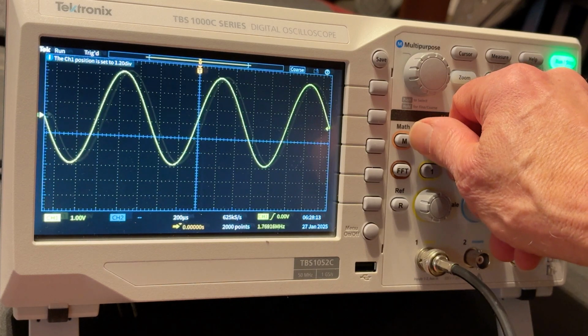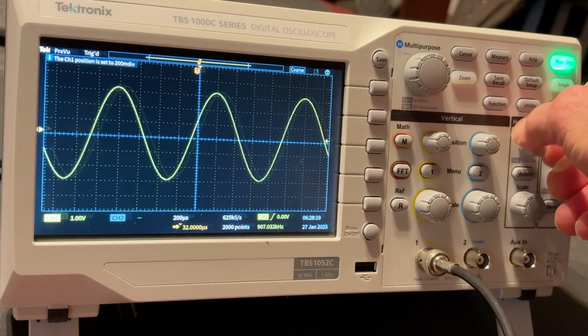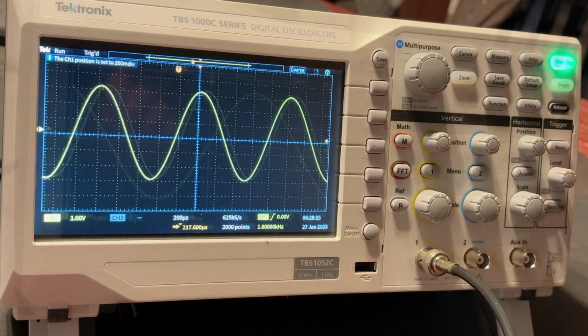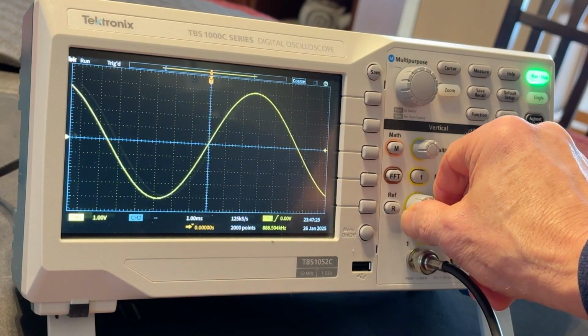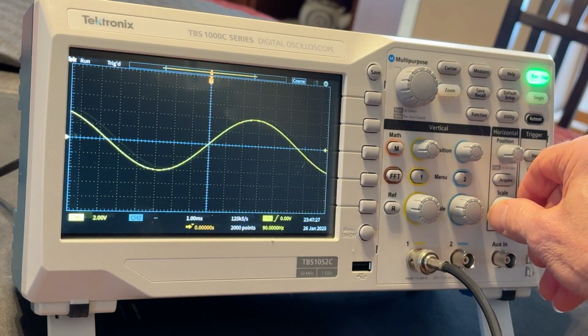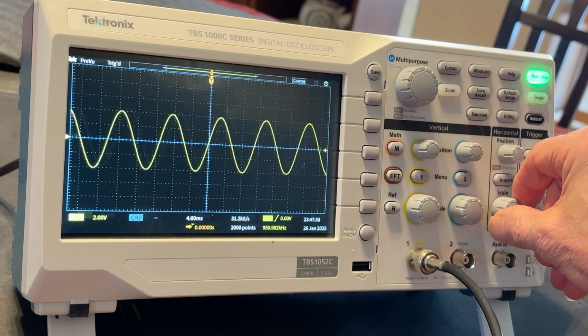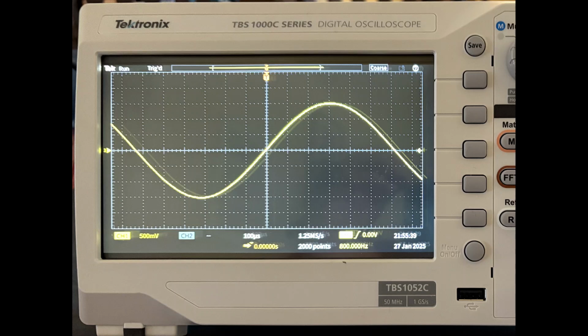The smaller knobs above these controls allow you to adjust the position of the waveform on the screen. You'll want to do this to make measuring the waveform easier. Turning the large knob allows you to zoom in and out to see more or less of the waveform on the screen. Important note: the knobs only change the way the waveform is displayed on the screen. It does not change the value of the amplitude or the period of the waveform. Also, to get the greatest accuracy when making measurements, adjust the knobs so that just 1 or 2 periods of the wave are on the screen.